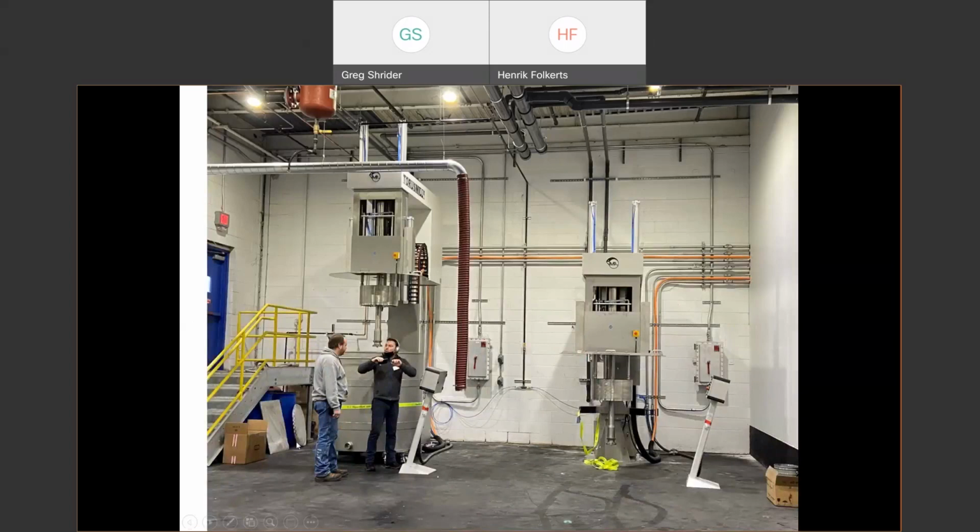Okay, so here is my dissolver blade back here. It's not installed. This particular customer is a large-scale dispersion manufacturer out in the Midwest, and they purchased two systems. They first push their container there, and do their predispersion with the cowls blade. When they reach the required particle size, all they do is push a button right here on the control board, and that basket gets lowered, and this whole thing turns from a dissolver into a basket mill. Now I'm actually milling in my large container, so I don't have to use two pieces of equipment. I can do everything on one piece very efficiently and very quickly.